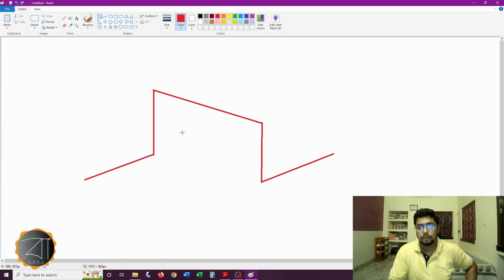This shear, we don't consider it in the case of structural designing, but whenever we are doing the BBS, we have to give some provision for it, kept as 5% for wastage and lappings, all those things. So we have to think differently. We have to think more like an executor or a site engineer than a structural designer. This is the main difference between a person who is making a BBS and a structural designer, though both of them are highly interlinked.